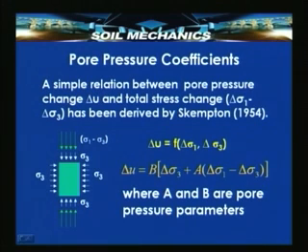are applied. So, here it is, there is a triaxial specimen, we first apply sigma 3 and then we apply the deviatoric stress. The change in pore pressure, net change that will be produced, will obviously be proportional first to the incremental stress in the lateral direction, that is delta sigma 3, and a component of increment due to the deviatoric stress. This is an obvious relationship between the change in pore pressure and the applied stresses.